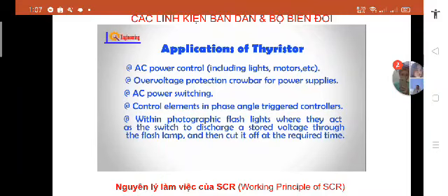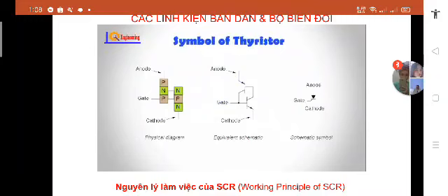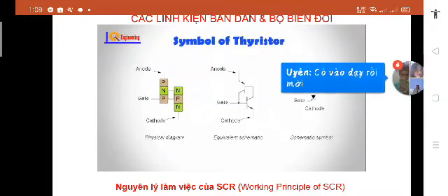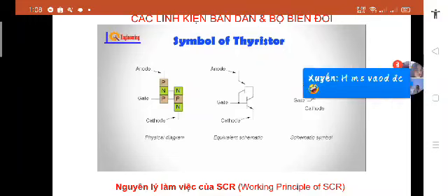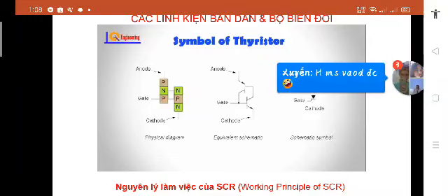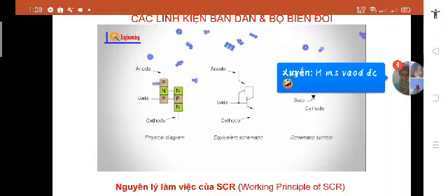Thyristors are able to switch high voltages and withstand reverse voltages, making them ideal for switching applications, especially within AC scenarios. Symbol of thyristor. The silicon-controlled rectifier, SCR or thyristor symbol used for circuit diagrams seeks to emphasize its rectifier characteristics while also showing the control gate. As a result, the thyristor symbol shows the traditional diode symbol with a control gate entering near the junction.